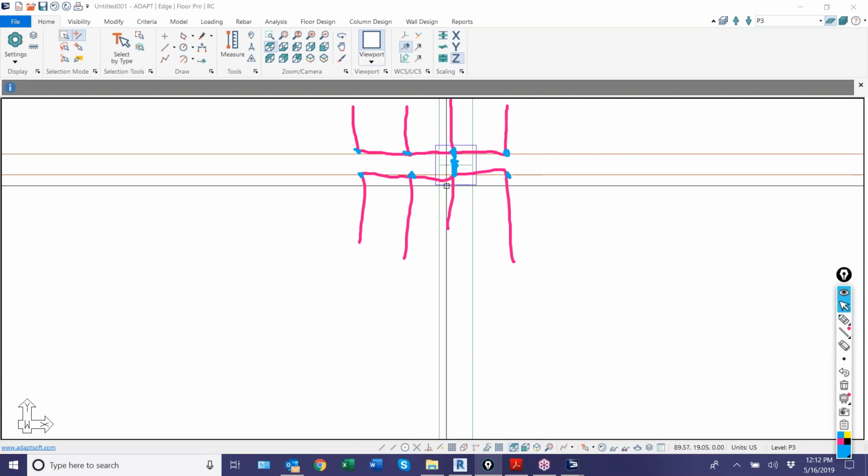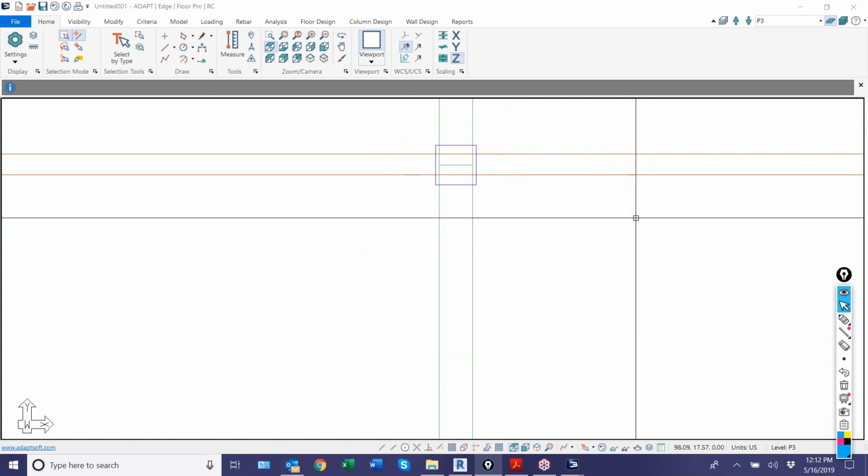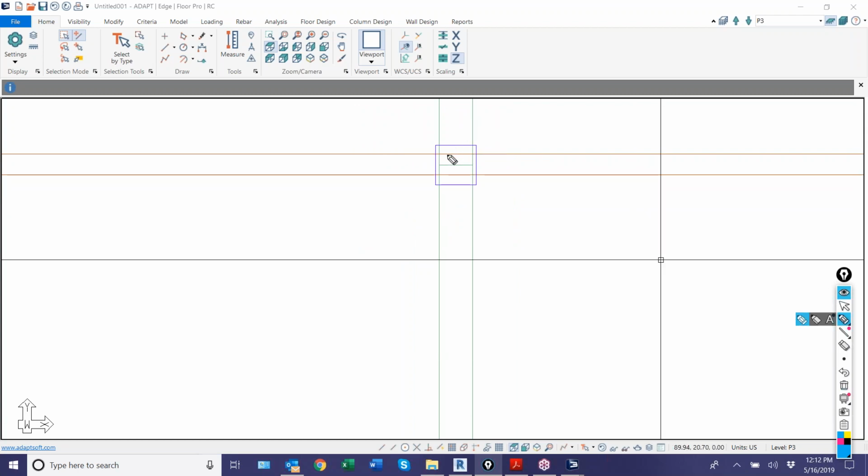There are some conditions where, for example, if I take these beams and move the beam, let's say to face of column, like so, now what could happen potentially is this beam could jump over this gap and maybe get shifted to this edge of this opening here, and the column gets shifted and this beam gets shifted all to that node, and then this slab could potentially become disconnected from the beam. So there's ways to handle that.